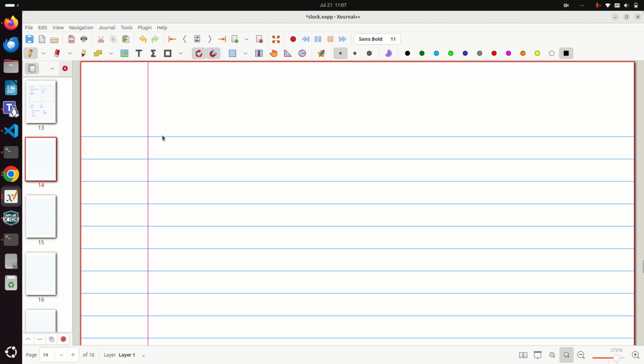lines. So which are the two lines? They should have two data lines, one for transmission and one for reception. And here we use the terminology master and slave. So one line is the clock line, the other two lines are data lines, and we refer to the devices as master and slave.